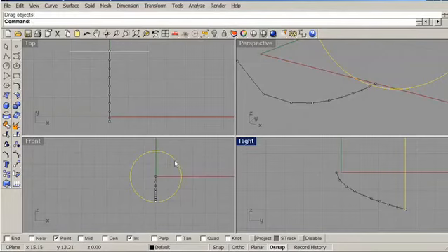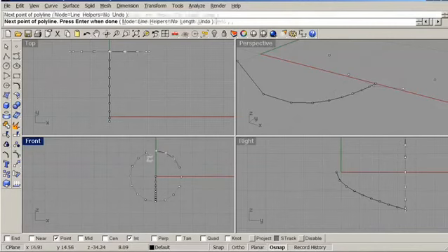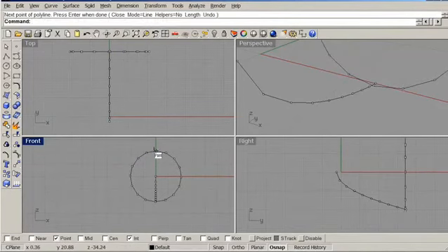I want to take this curve, and I need to divide it, again using the divide command. Since I've already selected it, I need to just say how many segments. I'm just going to accept the default, and in this particular case, let's make 16 segments. And again, we can delete the curve and just create a polyline. Okay, so now what we've got are the 2 lines that define our parabola.